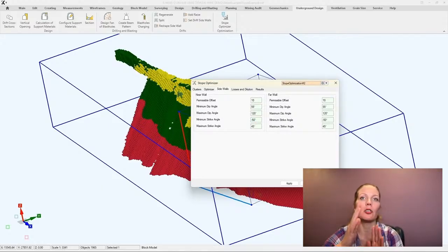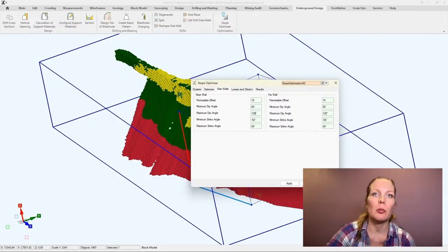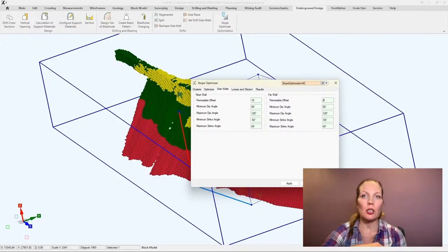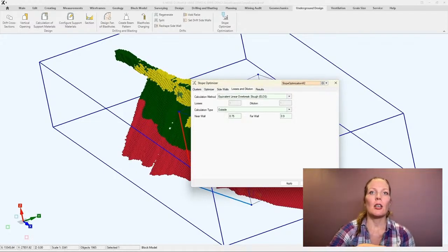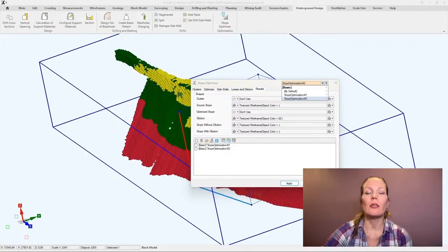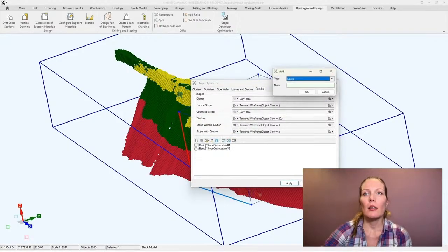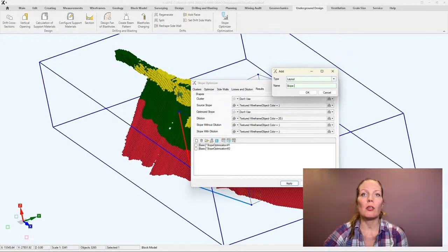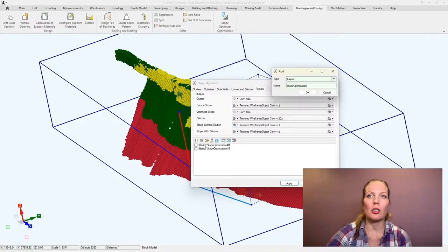So next come geotechnical constraints. Removing weak zones, limiting spans, enforcing sidewall stability, and if there is a section along the drift with unfavorable fracturing, that section is simply marked as inadmissible and excluded even if grade is excellent. This is crucial in faulted underground gold mines where rock quality can change dramatically within a few meters.